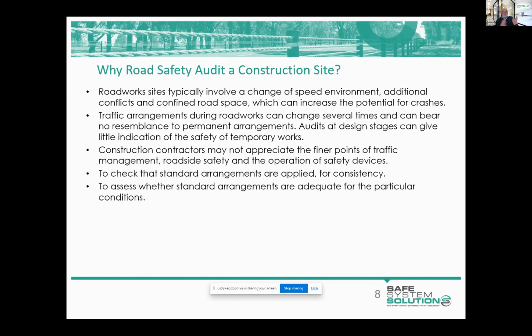Yeah, and I'm glad we've got a little bit of discussion in that space, Ken, because as I said, when we rip up a piece of road, we have changed those driving conditions. Yes, there could be loose material, but we don't need to be down to 40 kilometres an hour. The only reason 40k an hour was introduced into our signing Australian standards, before the guidance material, was for worker safety. It wasn't for poor management of sites, or for the inadequacies of the way the site was managed. It was for worker protection.